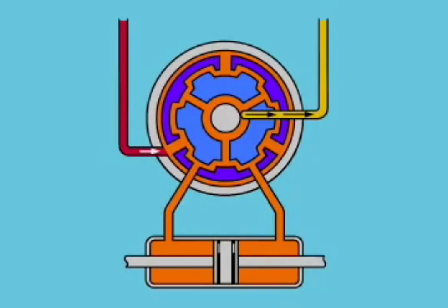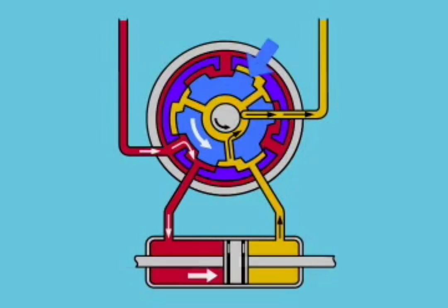In a rotary valve type, although the principle of operation is the same as in the four-way valve type, a rotary valve is used instead of a four-way valve. A torsion bar, which moves according to the steering shaft input, controls the input shaft to switch the hydraulic channels.